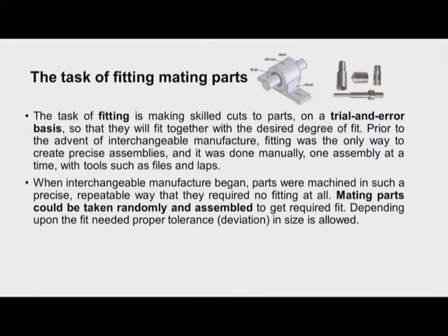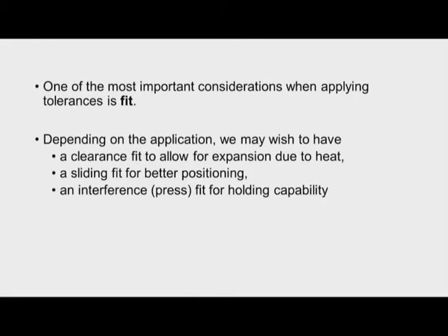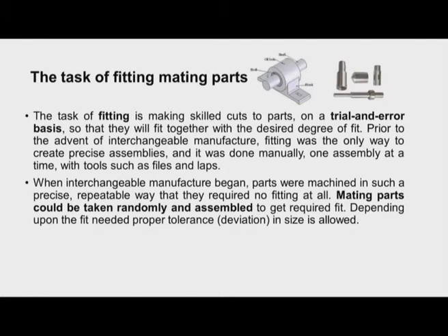Now let us try to understand what is the meaning of fit and what is the task of fitting the mating parts. We can see here we have a bore hole, a part wherein there is a hole, and then we have a bush and then there is a shaft. We have to assemble all these three parts. Now we should understand that the bush will be in contact with the body of this particular bearing, and there should not be any rotation or movement between bush and the body.